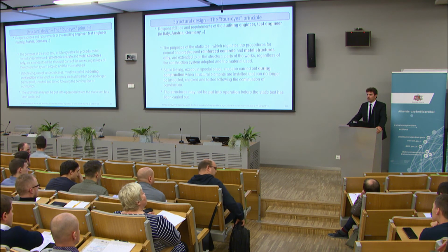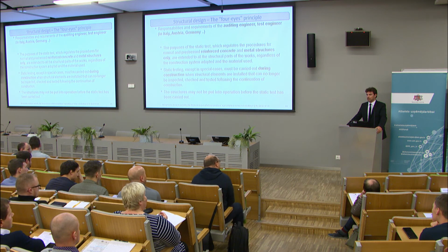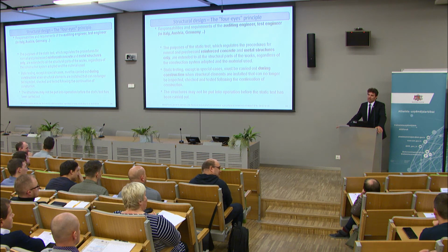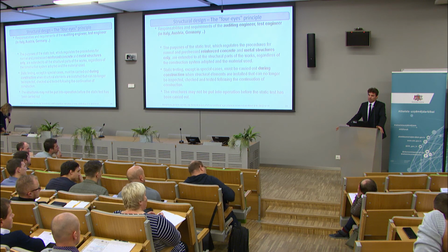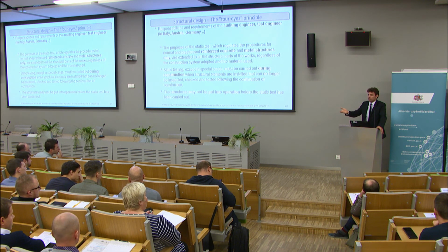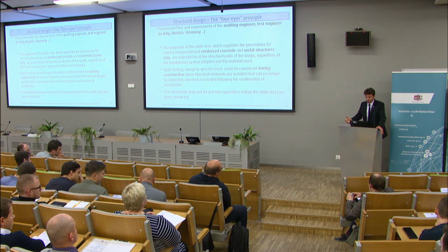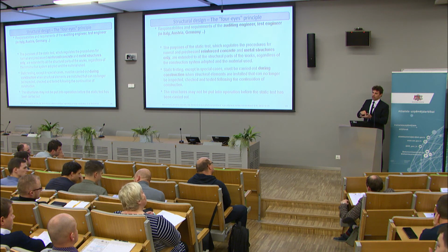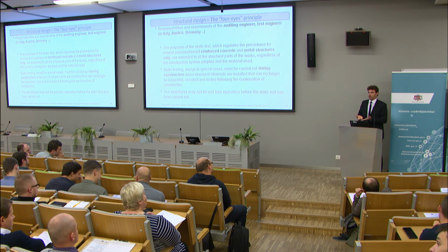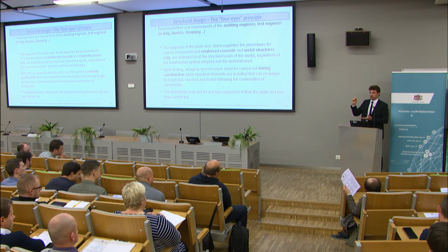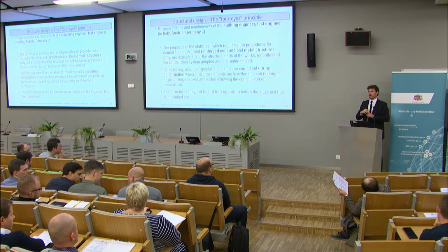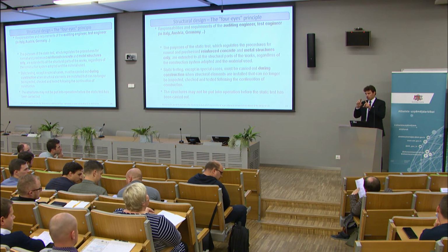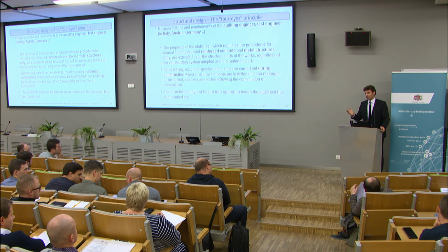A designer doesn't do testing. Either you can search in the literature, but usually this is done by material and construction companies that, for example, make bricks and then run tests, of course perhaps 100 tests. It is well specified in annexes C and D of the Eurocode. It is also related to the number of tests you execute. If you make just 5, you of course have a very high beta parameter. If you make 100 or 1,000, since you have a higher number of tests, you are allowed to reduce this parameter. So it's something that engineers get and don't compute by themselves. Thank you.